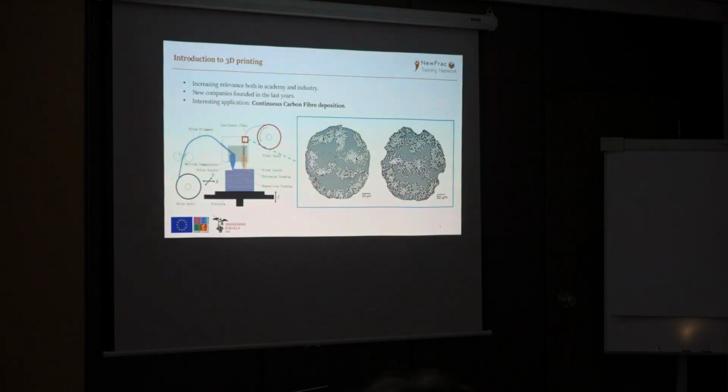And have you considered the effect of residual stresses? No. We are considering just a brittle analysis, since for this kind of structures, especially when the carbon fiber is aligned with the direction of the loading, the carbon fiber brings all the load, so the behavior is basically brittle. So you just have a small deflection, but no.